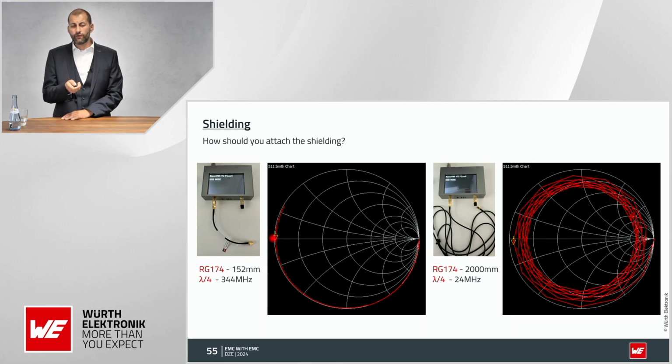This short circuit is exactly at lambda divided by 4. This is the spot where there is the highest impedance transformation. An open becomes a short. But what does that matter for our application, or in this case for our example?